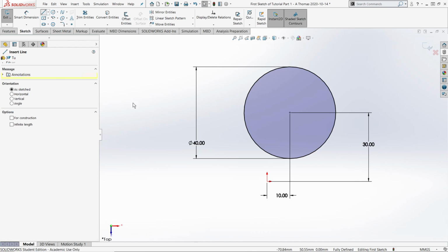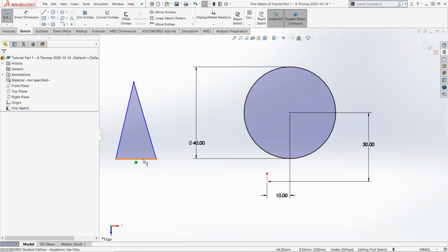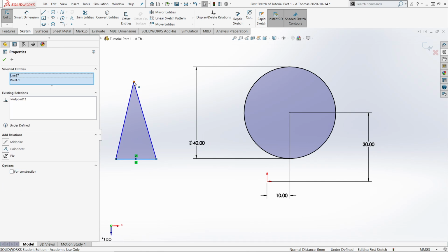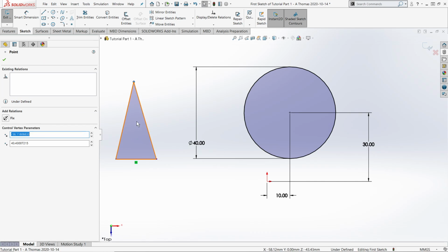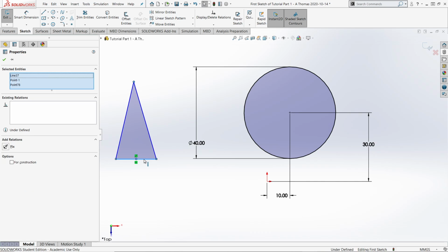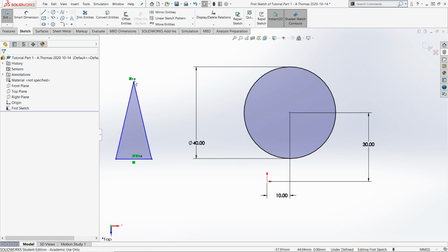you may design something, right? Like if I make this triangle, I let it do that automatic horizontal. I want to make this like an isosceles triangle, so I'm going to click on that midpoint at the bottom, control click at the top, and click at the top, control click that midpoint, and I'm going to, why is it bullying me? There we go. I'm going to click vertical, so now isosceles.